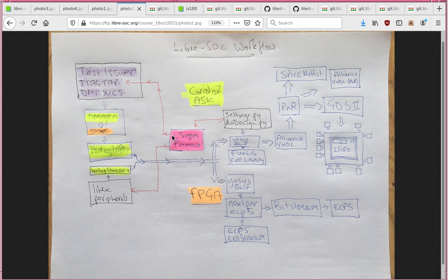And then you can make the choice to either compile it to FPGA, where the tools will take care of connecting things in. Yosys will take care of introducing you to the ECP5 cells, and on the ASIC side, Yosys will take care of introducing the cell library, the standard cell library.